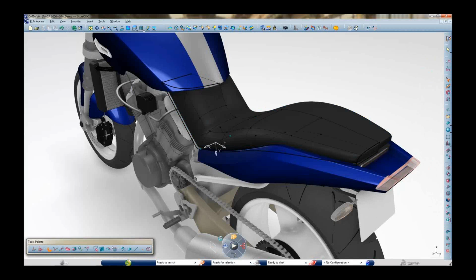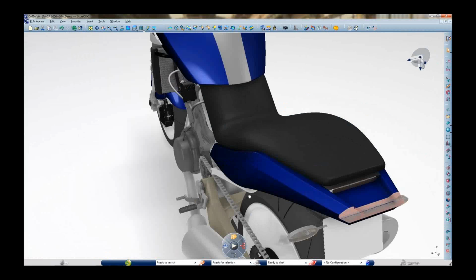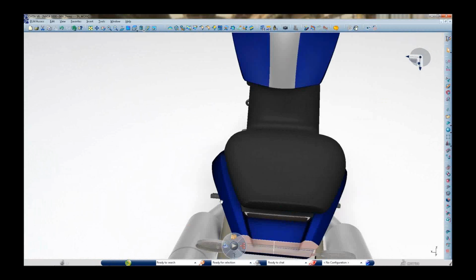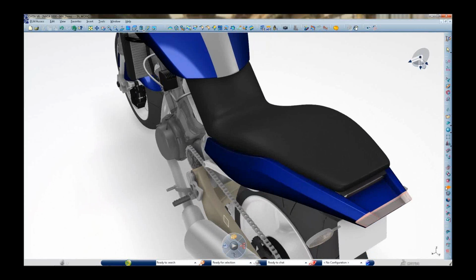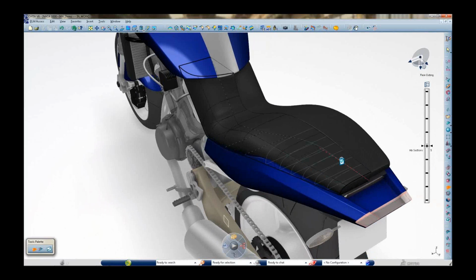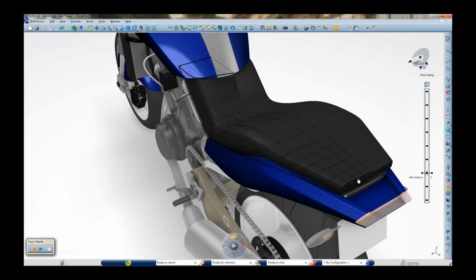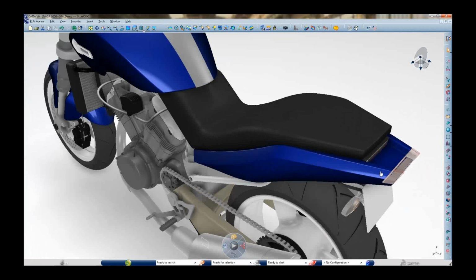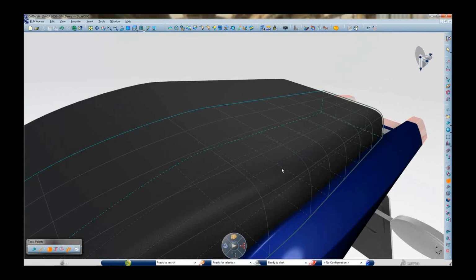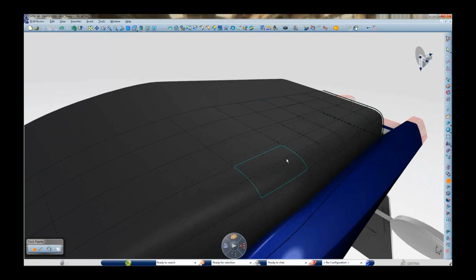So here, for example, we achieve a first level of the overall shape we would like to achieve. We do automatically the symmetry, and then we are starting also now to study the materials in real time. And when you want to have more detail with this mathematics, you just need to subdivide the area where you want to add more details. So for example, here we divided the back of this seat in multiple faces because we want to add a handle on this seat.